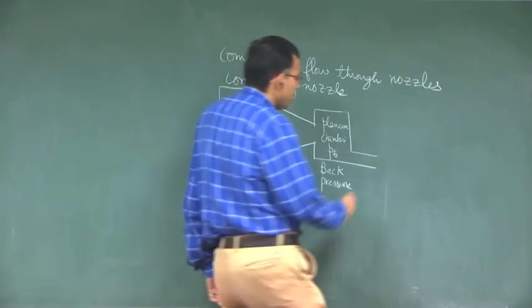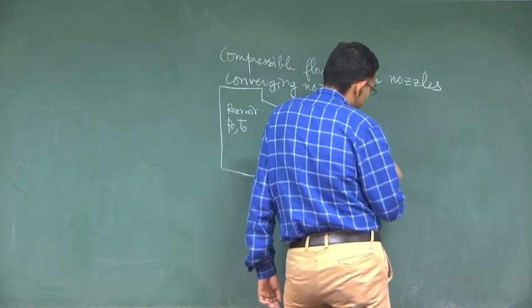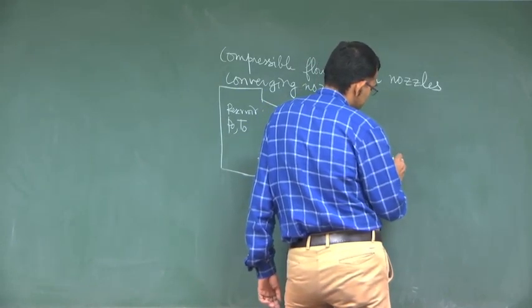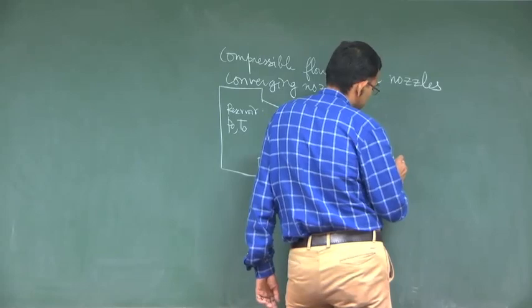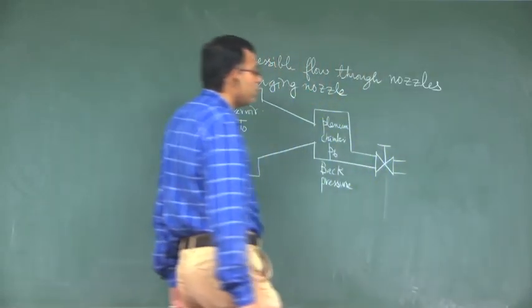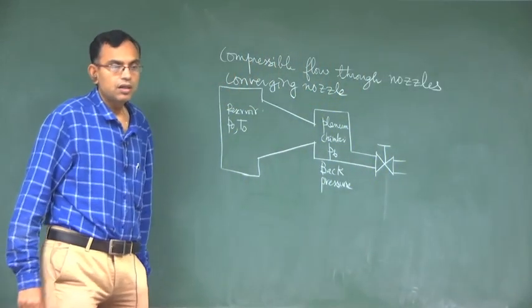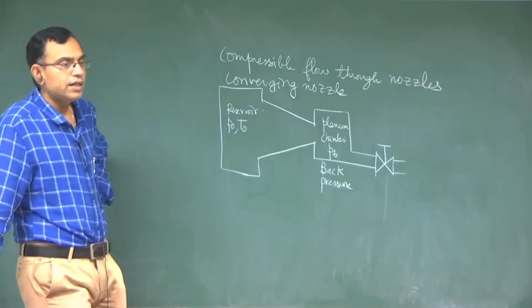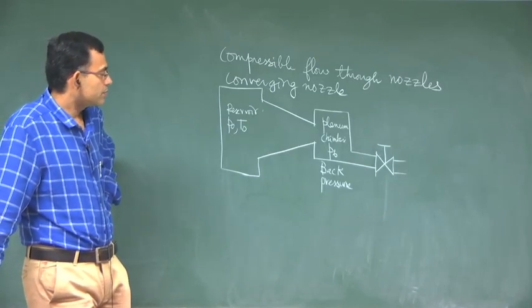How do you control the back pressure? Typically there is a valve. By regulating this valve, you can modulate the back pressure.